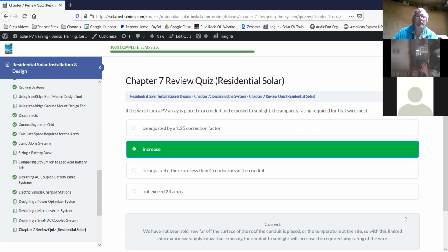Yes, if conduit is lying on the roof, but depending upon what the roof is, we just put cinder blocks up there instead of paying $12 for this fancy little thing. Just put a like $2 cinder block up. But that's just whatever. That would work if you're working on a flat roof. But if it's a shingled pitch roof or something, then the better solution is to run the wire underneath and penetrate under your array, and that way visually it just looks a lot better.